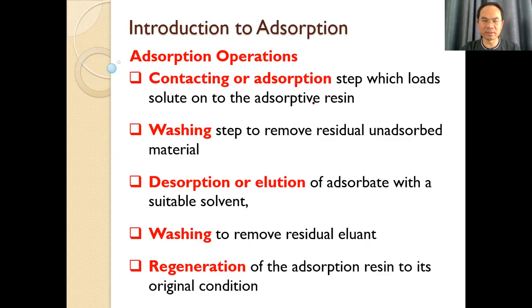The next step is washing. The washing step removes residual unadsorbed material. If we feed material, only some part of the solute can be adsorbed or accumulate on the surface, but there is also some unadsorbed. In this step, we wash to remove the residual unadsorbed material.